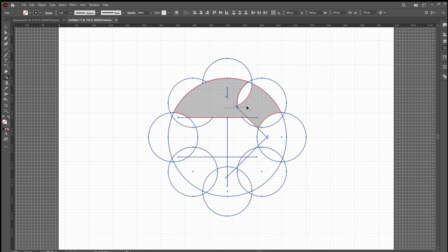So I'm just left clicking and dragging, nothing more. I'm not doing anything extra. If you want to delete something like this line in here, hold alt, and you see your mouse will change from plus to minus. So come to this, hold alt and left click, and it disappears. But you don't need to do that actually. So just continue drawing your shape.